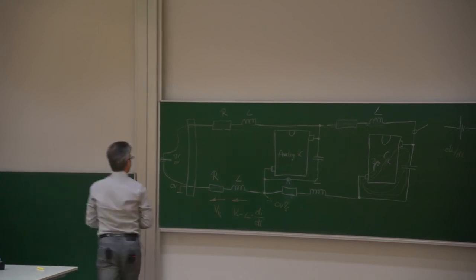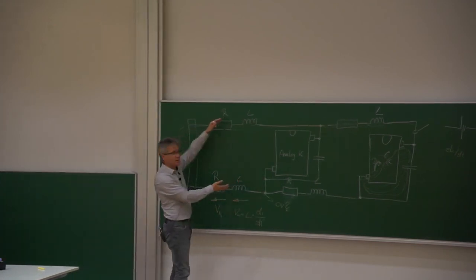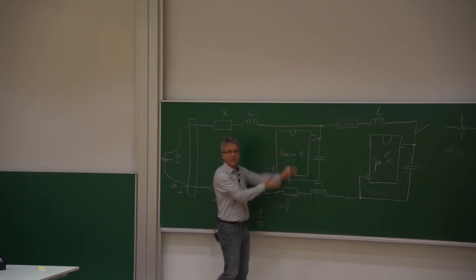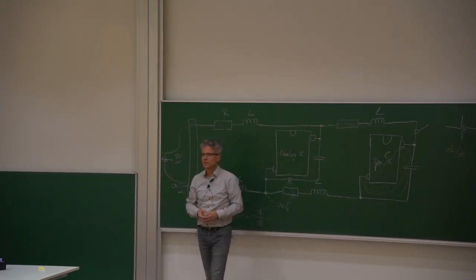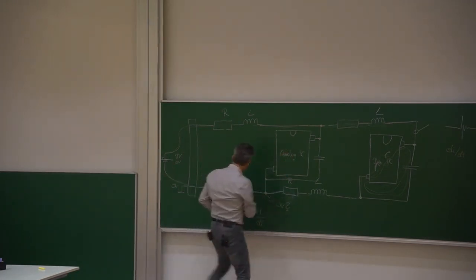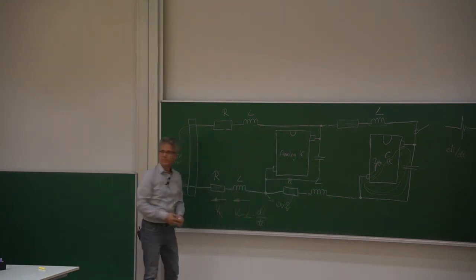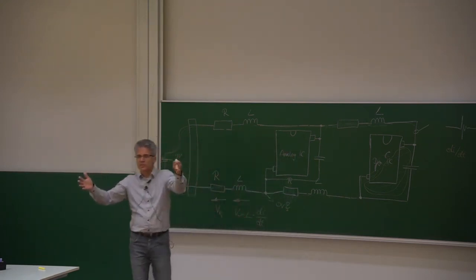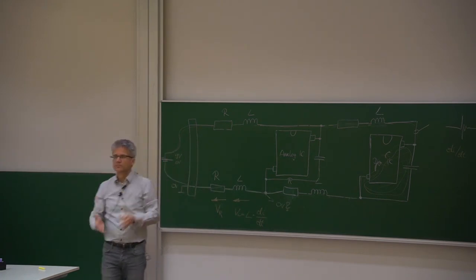Exactly, why should the loop area be that big? So maybe we can make the loop area smaller. Small loop area, small parasitic inductance, small voltage drop. So place the VDD and ground connection close together.